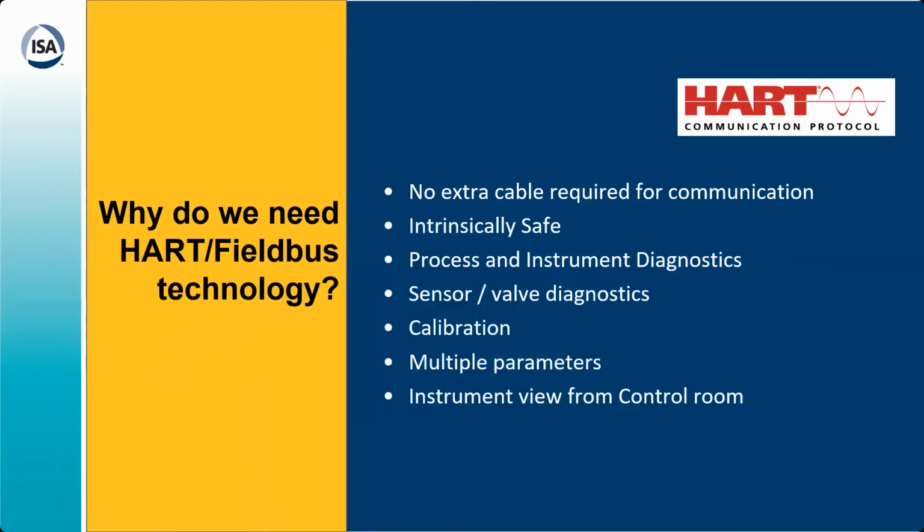So why do you need HART? As I told you, basically it is intrinsically safe technology. It gives you the instruments and process diagnostics. It gives you the sensor and valve diagnostics. You can do the online calibration by sitting in the control room. It gives you the multiple parameters. It gives the instrument view from the control room. All those things are there.